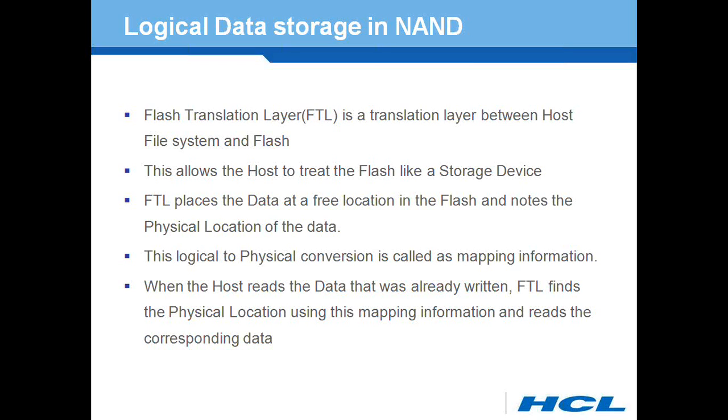This FTL places the data at a free location in the flash, and it takes care of storing the physical information corresponding to each logical data. This information is called mapping information. An efficient mapping algorithm will give you higher performance.